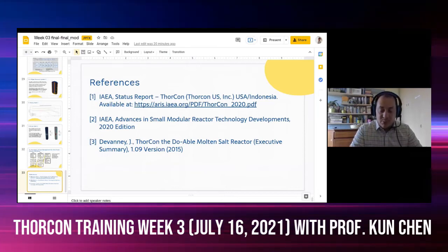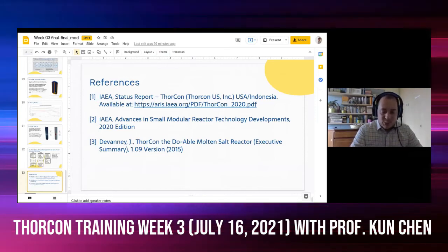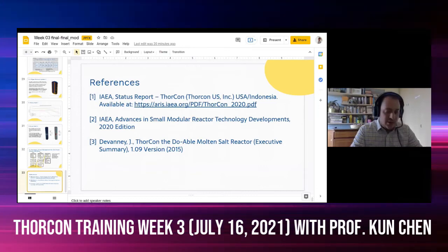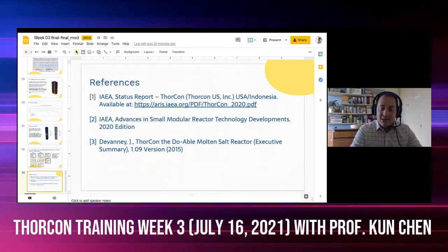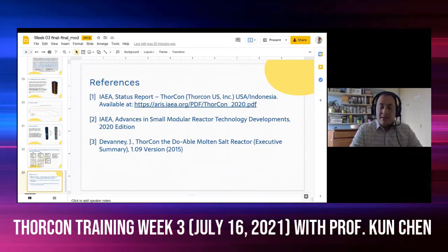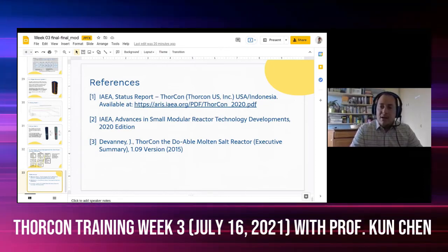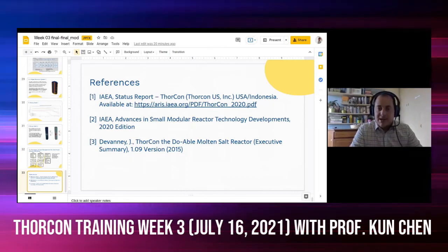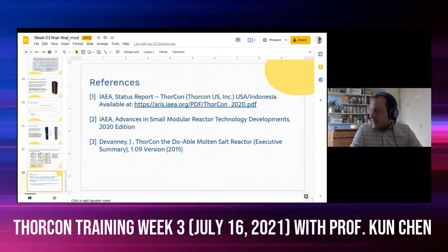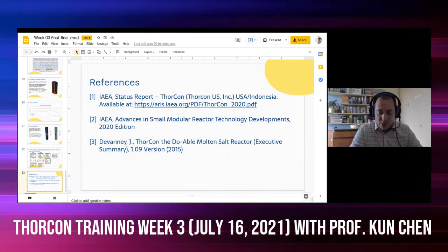So the Monte Carlo code Serpent has burn-up capabilities with the solution of the exponential matrix, the Chebyshev rational approximation, and recently, as included in the standard version, no more in the extended developed one, the possibility to move material around to simulate even reprocessing, but in our case, gaseous extraction, noble metal plate-out, and feeding of makeup fuel, and if needed, also of thorium.